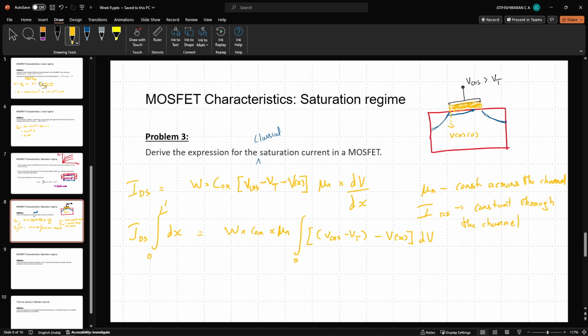So this is our 0 reference level. Okay, so 0 to Vx, or rather VL dash in this case. So from that, what we will get is I_DS is equal to, or to be more precise, it won't be V of x. Since we have applied VDS, the maximum voltage it can achieve is VDS. So now this is going to be W by L dash into Cox into mu n times VGS minus VT into VDS minus VDS squared by 2. Yeah, so this is the current in the channel.